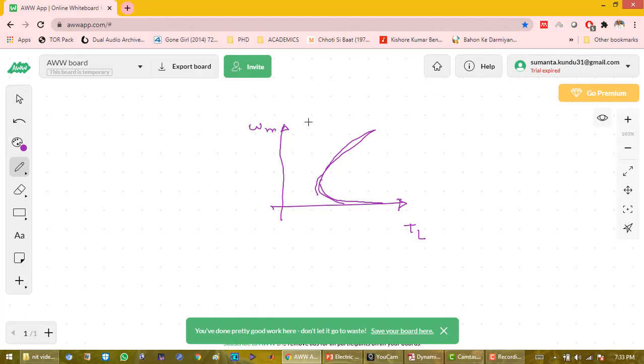but actually the train has negotiated upward and downward slopes. So consequently torque due to gravity, which varies with position, is also present. Furthermore, when a train takes a turn, the friction force of wheel changes substantially. Thus, traction is an example where load torque also depends on position and path followed. So this is the nature of traction, which depends on speed, position, and path. This is a typical nature of tractional load.